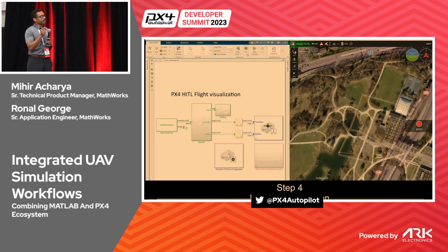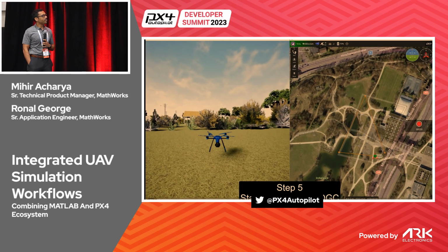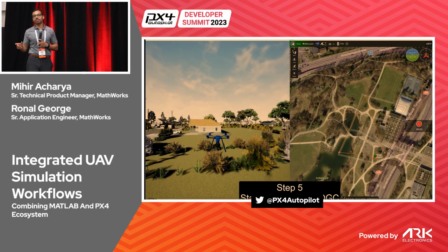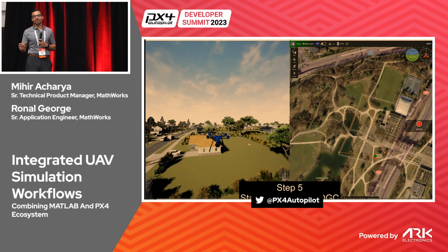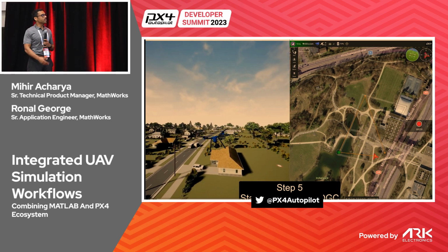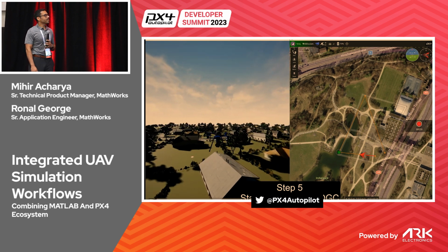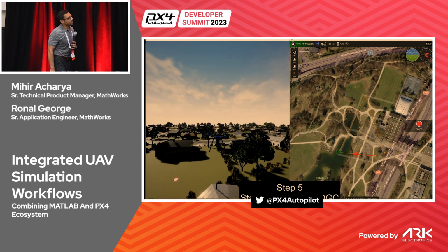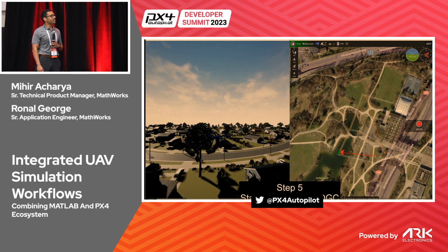You want to test these out? With this, we can actually start injecting some of these failures directly to your plant. So here's a simple flight that I was doing where everything works as expected. You'll notice a difference. Once I've deployed this plant model, things start running a lot smoother. My visualization's the only thing on my host computer, so no bottlenecks here. Right, so this is a simple straight mission. 3 waypoints, go there, come back and land. You can see on the top in QGC, I have great number of satellites, so GPS is valid, nothing's wrong.